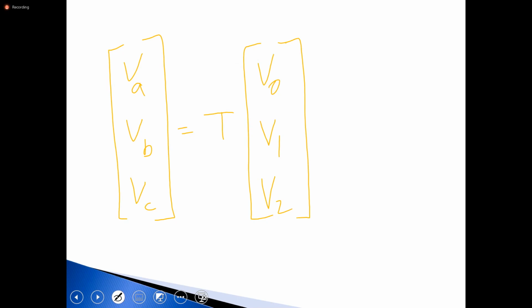The answer you get here would represent per unit. So in order to get the actual voltages, which is what you're being asked for, you need to go back to the opening part of the question, which tells you where the line is located. Where is this line located?